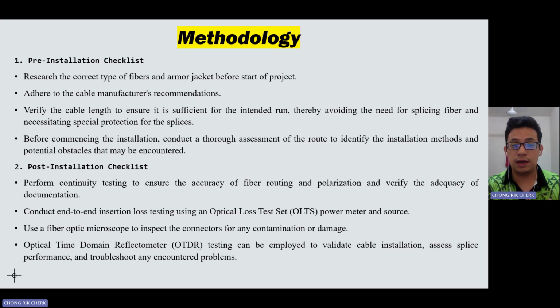We then use a fiber optic microscope to inspect the connection for any contamination or damage that may occur during installation. And OTDR, or optical time domain reflectometer testing, should be employed to validate the cable installation, assess splice performance, and troubleshoot any encountered problems.